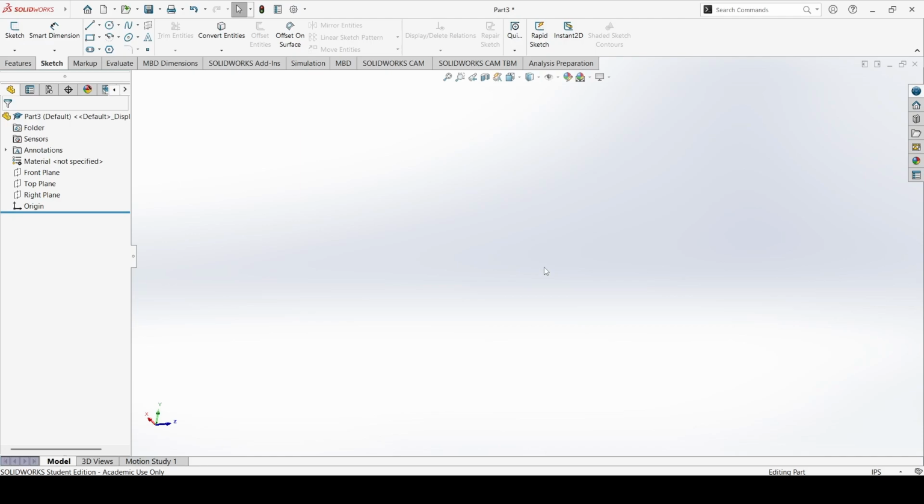All right, today we're going to talk about 3D sketching. And 3D sketching is a little bit different than 2D sketching, considering it's in 3 dimensions. But even starting off by going under Sketch and then 3D Sketch, it starts off different. You don't actually select a plane to do your sketching on. It actually does it in kind of all three.